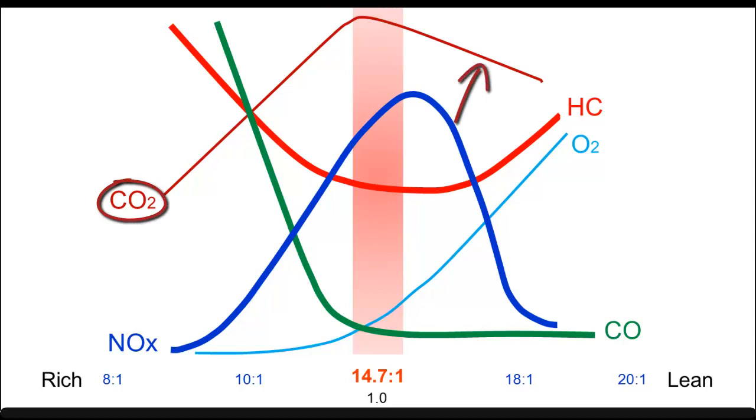Carbon dioxide low or off-peak at 9.49%. Oxygen high at 6.26%. Lambda at 1.43 represents leanness.